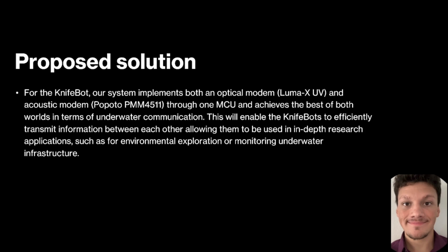Our proposed solution for the Knifebot is to implement both an optical modem, the Luma XUV, and the acoustic modem, the Popoto PMM4511, through one microcontrol unit and achieve the best of both worlds in terms of underwater communication, where the microcontrol unit will take outside environmental data such as clarity of the water, light sensing, any kind of contaminants in the water that make it murky, and decide which modem is best for operation.